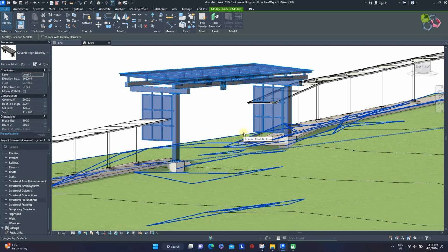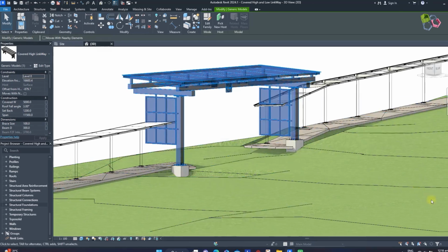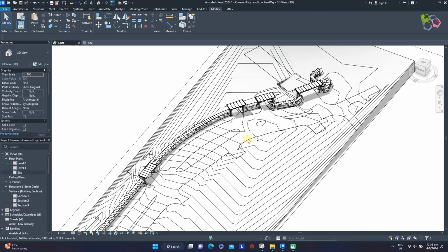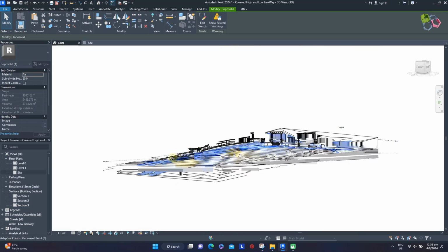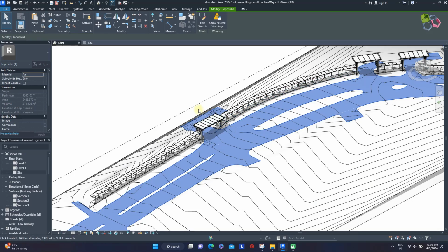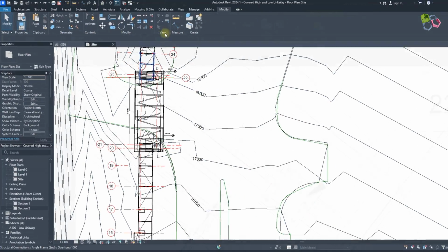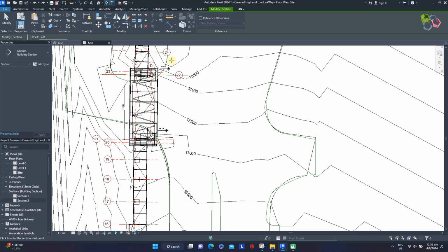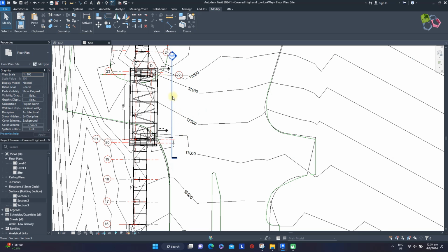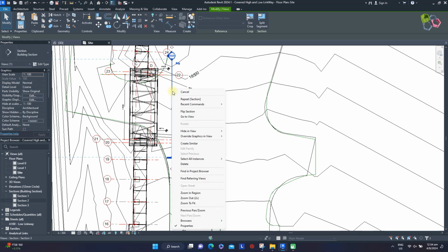At this stage, we will need the road structure for the reference level. Let's skip this road creation for now. Here, the road element for the project leading to the neighborhood premises. Not perfect, but to make reference for position and level. Go to site plan, add first Linkway. We need to create a section. Select this section icon, draw from here to here. Hit double arrow for viewing right sectional elevation facing the Linkway.